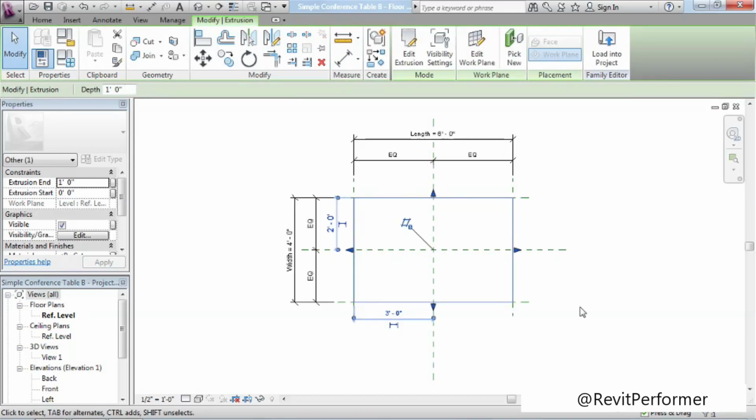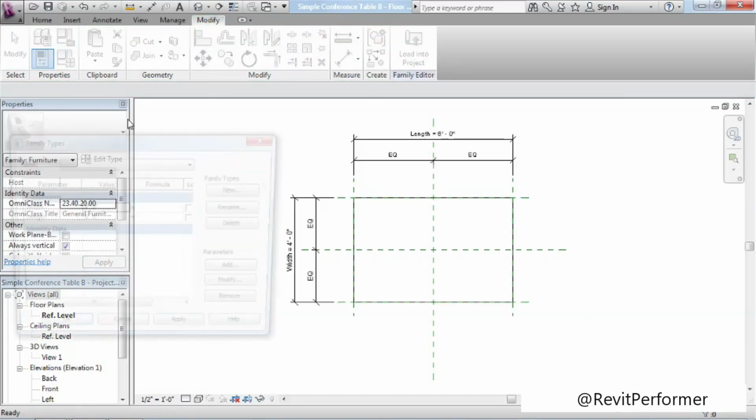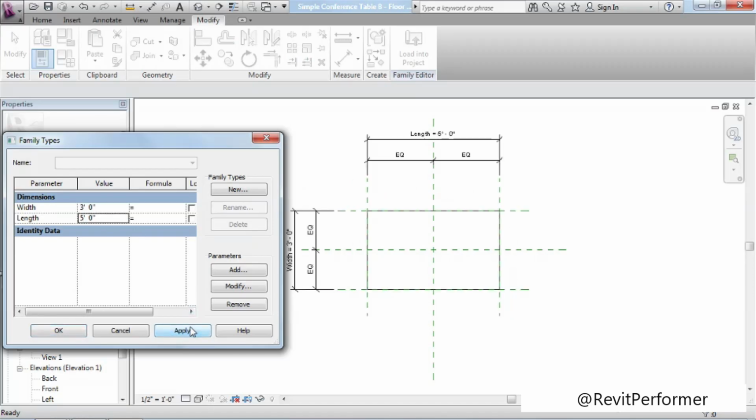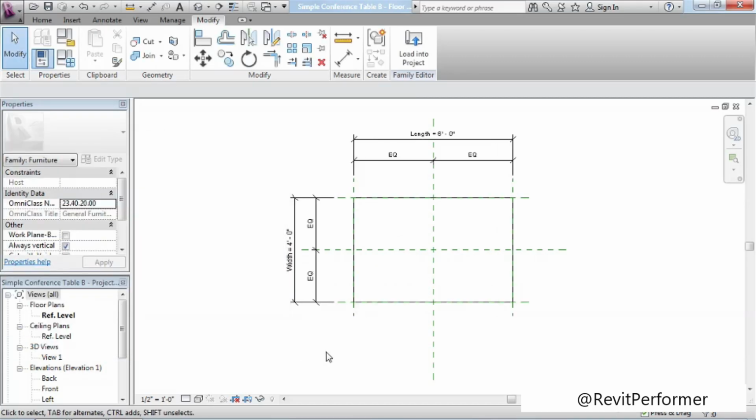I go to finish, and ultimately I really won't see anything different with respect to how it flexes. It's still going to flex the same way, but that's only because the geometry that we have on screen is so simple. Later, when the model gets more complicated, you're probably going to find that you're going to want to control those constraints a little bit more deliberately than relying simply on the automatic sketch dimensions. I wanted you to be aware that they were there and understand how they behave.